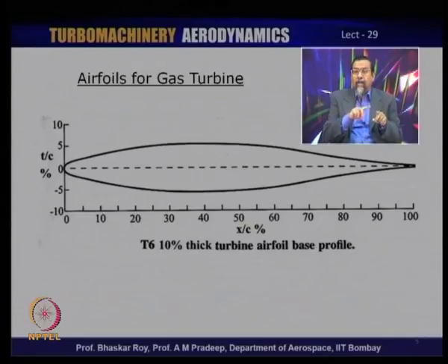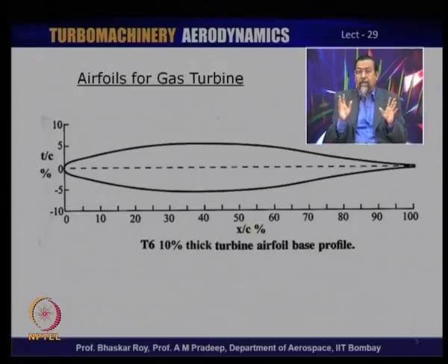Quite often you may have a circular arc camber or any other arc camber, may even be a parabolic arc camber, with a total camber of the order of 90 to 120, 130 degrees. We have discussed that in case of a turbine, that camber is far higher, quite often thrice that of a typical compressor camber. So, that is the camber on which this blade profile is distributed. This thickness distribution that you are looking at is available in many literatures very easily, and that thickness distribution is distributed over the camber.